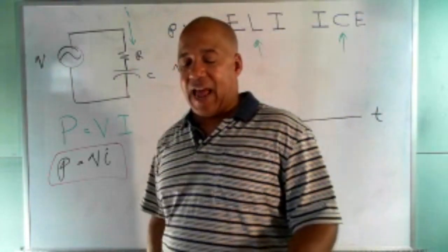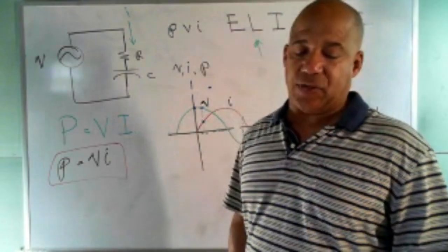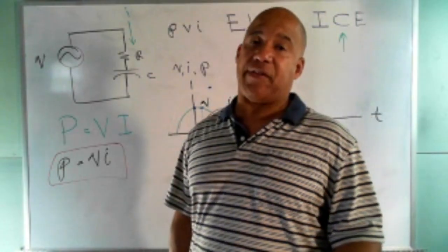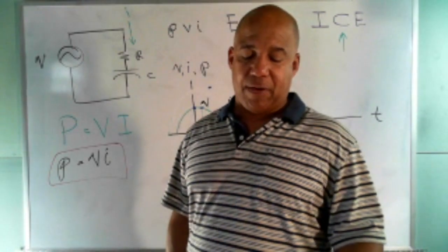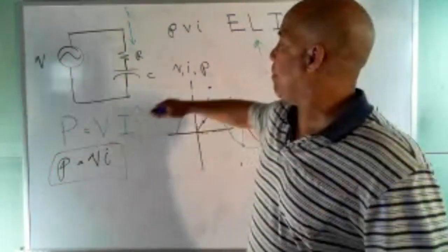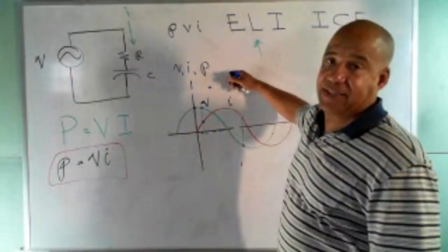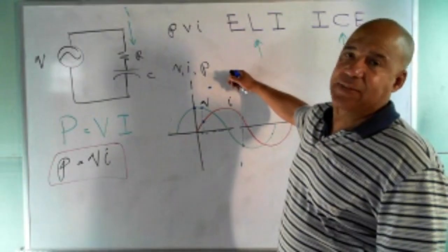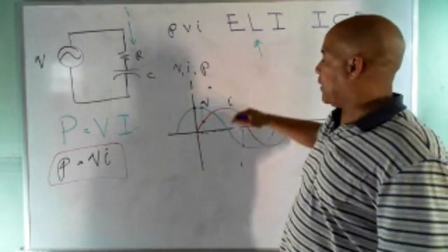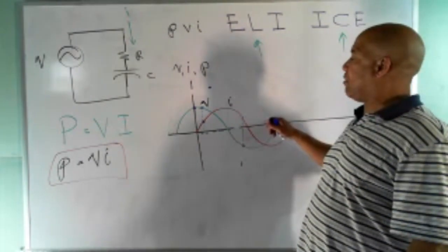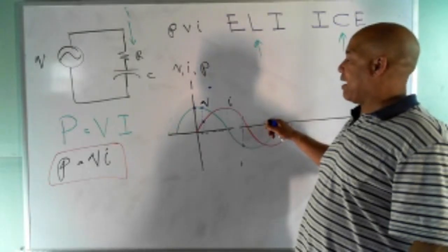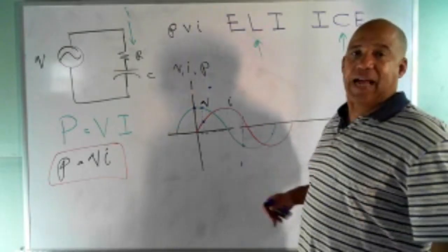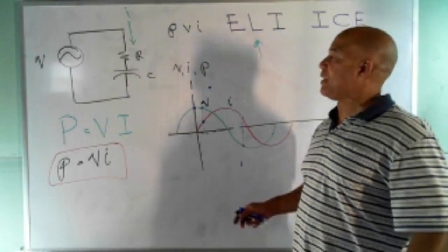Well, that last graph where you have resistance and reactance, you see a combination of the first two graphs. The power curve is not all the way above the horizontal axis, which means that it's not all resistive power, but it's not evenly spaced to where half the cycle is above the horizontal axis and half is below. So it's not completely borrowed power. It's a combination of both of those.